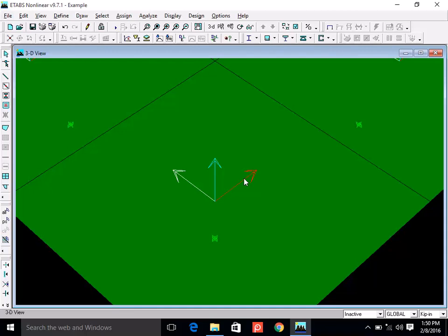Many students, they don't understand this local axis system. So when it comes to results, they are always confused about the results, and sometimes they make mistakes because they consider the force in one direction mistakenly to be in the other direction. These directions are important because you have to provide reinforcement accordingly, right? For example, if you are confused in these bending moments M1 and M2, and by mistake you take them opposite, then what is the end result?